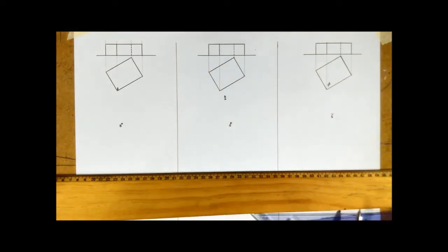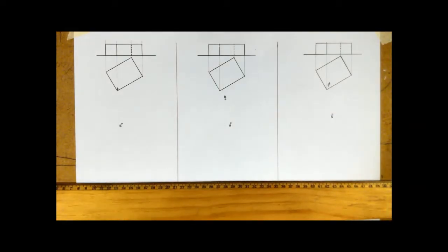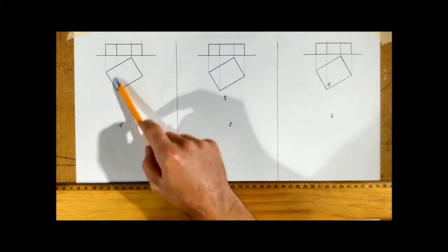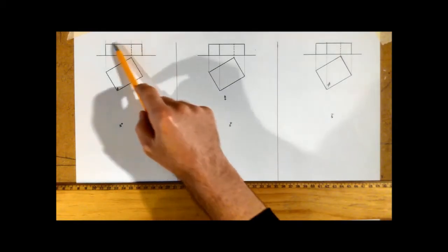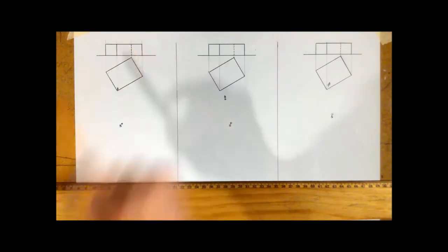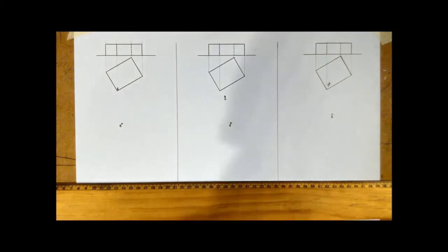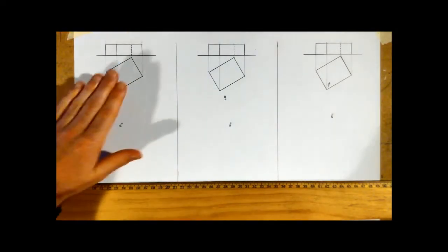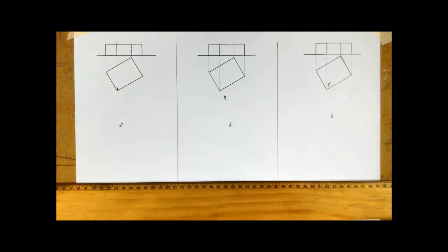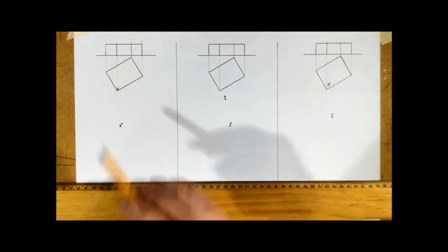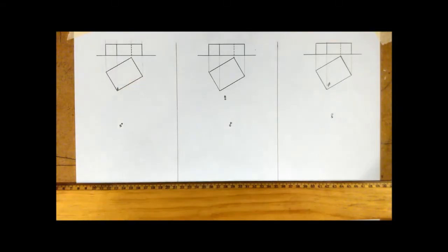Okay. So when we are given one of these questions, often we're just given an image, and for a lot of perspective projection you can complete the question by just using the plan view of the object. The only reason we really need the elevation is for the various heights. So if you don't need to discover a height, often you mightn't even have to draw the elevation. But for this case I just put it in there for understanding purposes. So you can see we're dealing with a rectangular box.